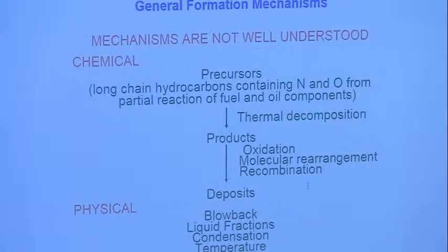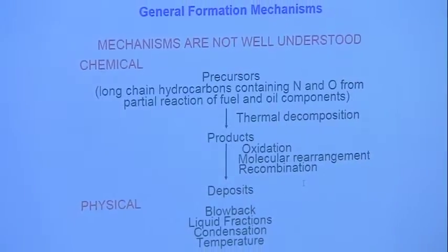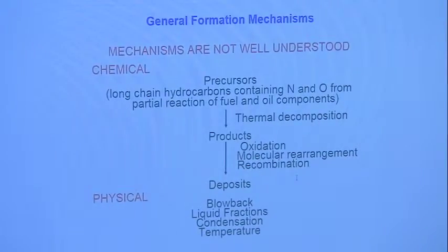As for general formation mechanisms, as I said, they're not very well understood. Just hand waving, you can say there are chemical mechanisms which basically cause deposit precursors. Quite often they are long chain hydrocarbons containing nitrogen and oxygen from partial reaction of fuel and oil components.